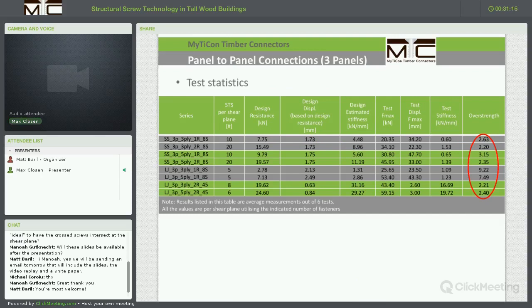What is easy now is to derive overstrength factors. So we can see that the overstrength factors range anywhere from between 2.2 to somewhere to 9 for the lap joints in particular there, where 9 seems very, very high in terms of overstrengths. An explanation for the high overstrengths here, I want to explain this quickly, could be that there are heavy reduction factors in Canadian design here.